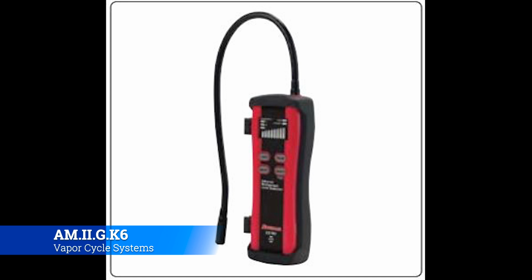Now, these systems don't have a whole lot of refrigerant in them to begin with. I mean, you think like a 12-ounce can could, in theory, top a system off totally. And so a little leak goes a long way in terms of damaging the system. So just something to keep in mind. But there are special tools out there. You don't necessarily need them per se, because there's a lot of people that get by without them. But they are super helpful if you can get your hands on them.